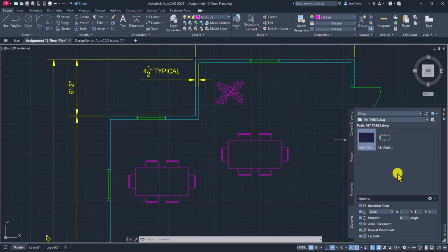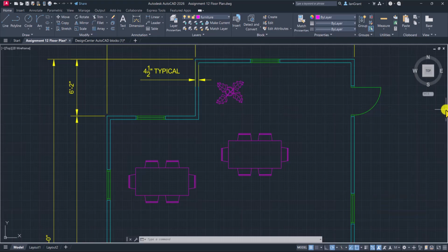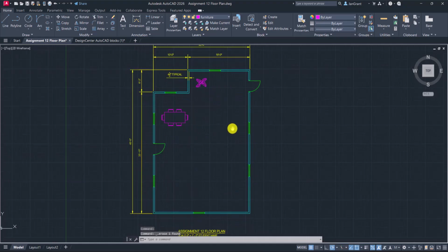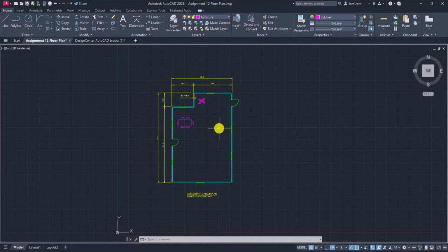And there it is. But this is how you would then be able to start to create a folder of all these pieces of things that you use all the time to be able to use them in other drawings and keep your files organized. You may even get a job in our industry at first, organizing these digital files. All right, so I'm going to close out of that, and so there it is, creating a floor plan with the scale factors in mind and changing your dimensions and bringing in blocks.